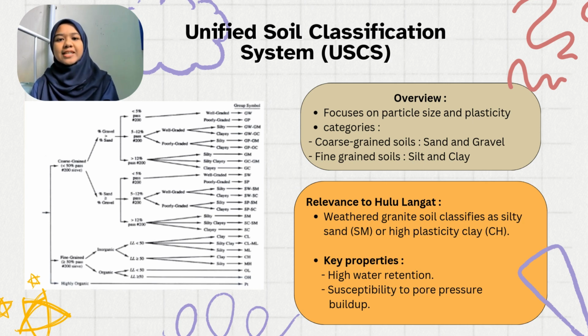In the Hulu Langat case, the weathered granite soil with high plasticity, which is CH, the soil characteristics are significant because of their ability to retain water, which can lead to pore pressure build-up and contribute to slope failure.